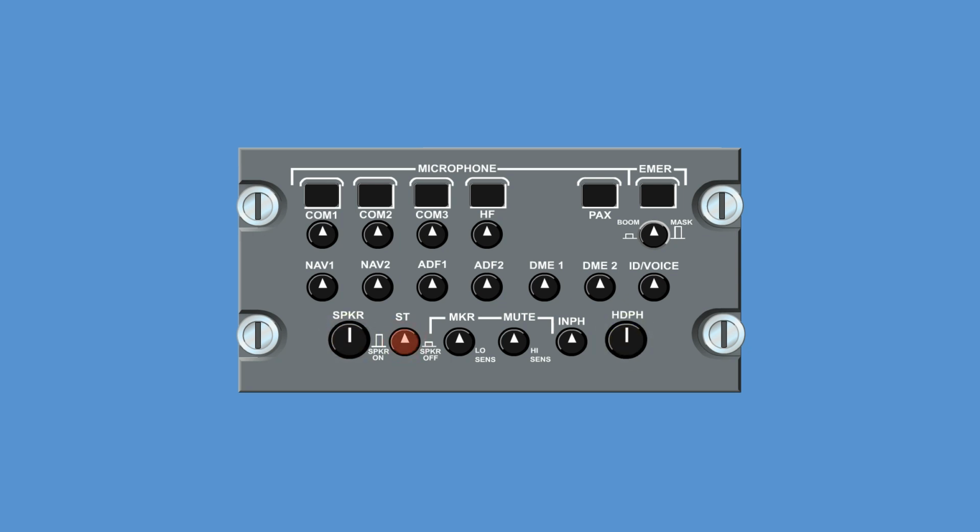The side tone level control is used to prevent undesirable feedback of speaker side tone audio into the transmitting microphone. When transmitting, both the on-side and off-side speaker side tone audio levels are lowered. In addition, the off-side headphone and side tone levels are lowered. When the side tone control is in the latched position, the on-side cockpit speaker is turned off. And when the control is in the unlatched position, the on-side cockpit speaker is on.